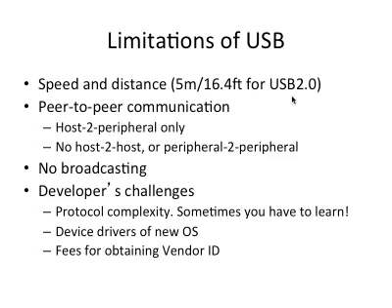The USB protocol itself is in fact quite complex. You need to spend time to understand the exact format of the messages. For new operating systems, you may need to design device drivers. Also, if you want to have a vendor ID, like the PCI vendor ID, the USB vendor ID is also not free.